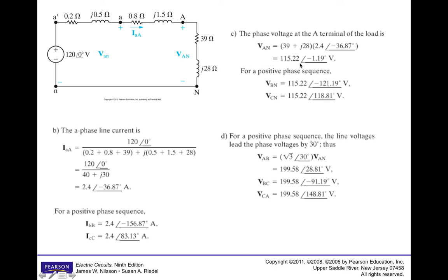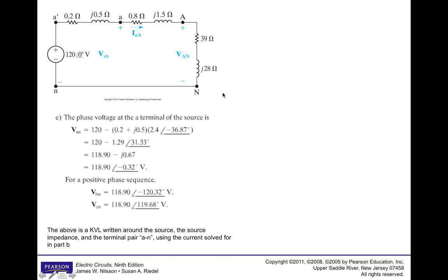The magnitude gives you some idea of how many resistive losses you had in your generator and your line, and the phase gives you some idea of how much inductance you encountered in your line and your generator impedance. So you're getting a little bit of a phase shift and a little bit of reduction in magnitude. Now if we look here at the generator terminals, what this is giving you is the actual accessible voltage.